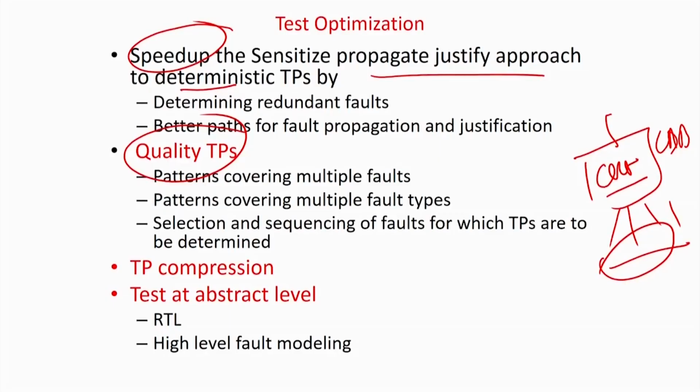Because as I told you, one fault, one pattern. I am not bothered to take that pattern. But one pattern, 10 faults, I am very happy with it. Because if I apply one pattern, 10 faults will be detected. So I need better quality test patterns.